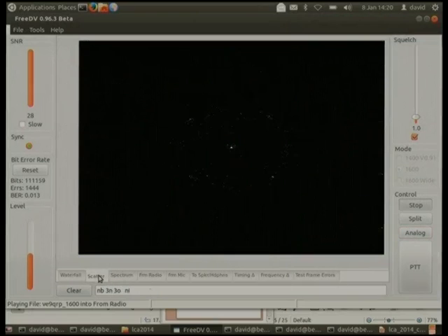Now, those of you who attended my modem talk will recognise this as a scatter diagram. In this case, it's a quadrature phase shift keyed signal, so there are 4 constellation points you can see. The constellation points are very tight, which means it's a really good channel, as it should be. It's just a recorded file off the disk. And the 2 outer points are the high power synchronization carriers in the middle, and they're only a 2-phase signal, so they're binary phase shift keyed.